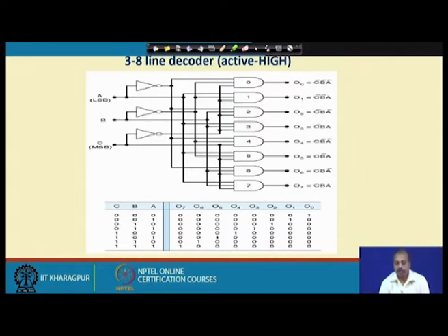We look into another example. It is a 3 to 8 line decoder. So, 3 bit input, if n is equal to 3, naturally I can have 2 power n, that is 8, as the m value, or the number of outputs that it can have. Now, here you see that O0 output will be equal to 1 when all these A, B, C bits are 0.